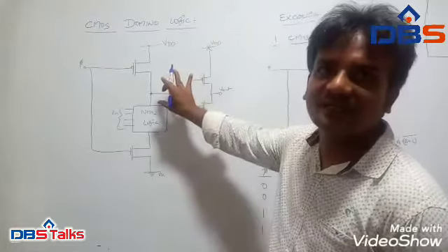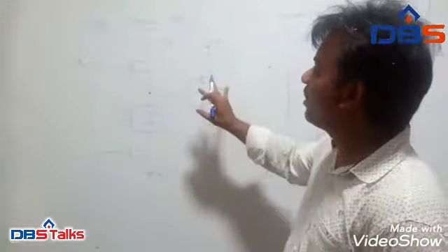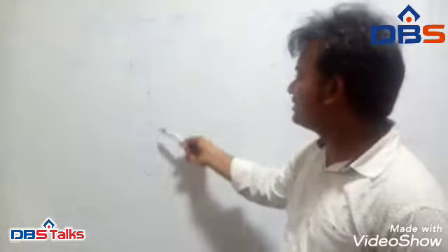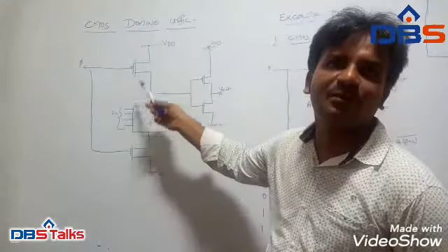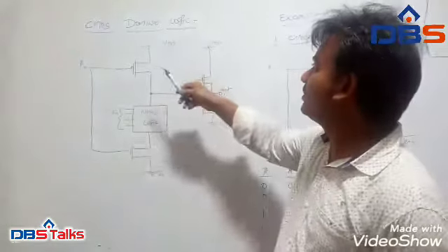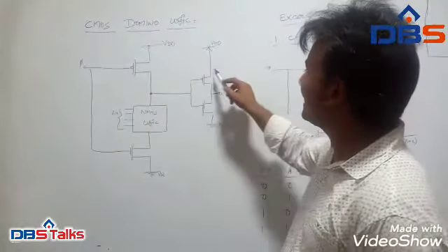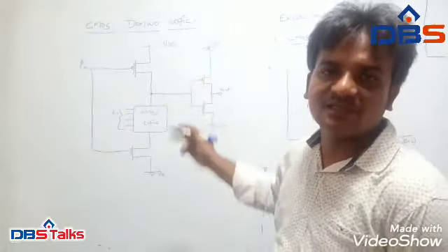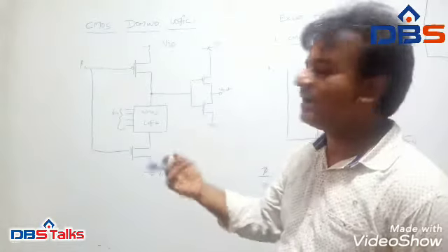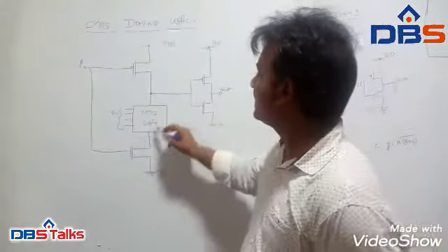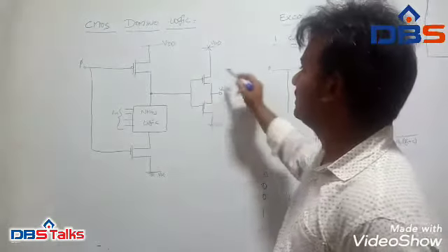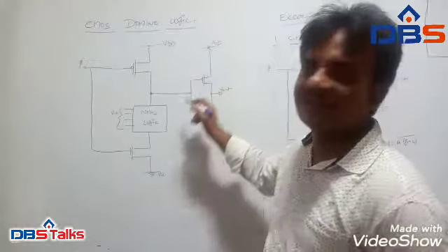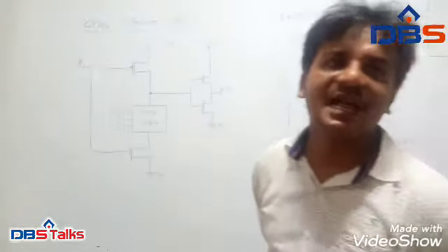Whenever we compare CMOS dynamic and domino logic, the precharge transistor and evaluation transistor and the NMOS logic are the same for both the dynamic and domino logic. Here in the domino we are adding an extra inverter for this design, to get a fast response to applied inputs, whenever we add the inverter at the output of the circuit. Whenever we add this inverter, we have different advantages and disadvantages.